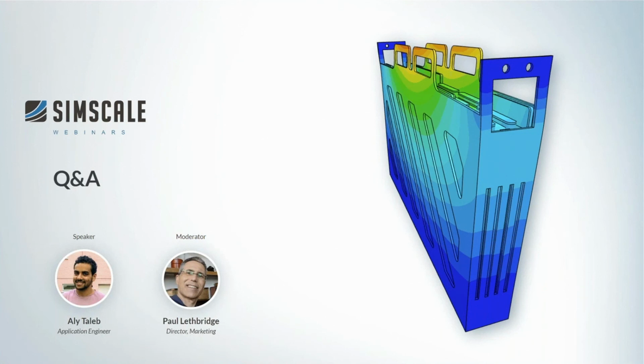Another question: how long does a simulation like this take to run, and what is the core hour consumption? How long a simulation takes strongly depends on the complexity of your simulation. For example, for the housing concept, the modal survey just took 10 minutes, and then the vibration analysis took 40 minutes. We were using 4 cores.